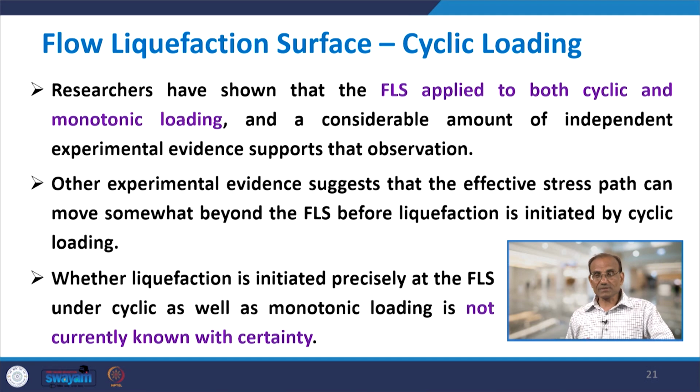So far we have discussed monotonic loading, but what happens if I change to cyclic loading? Researchers have shown that the FLS applies to both cyclic and monotonic loading. It is not only for monotonic loading, and a considerable amount of independent experimental evidence also supports this. Some experimental evidence suggests that the effective stress path can move somewhat beyond the FLS before liquefaction is initiated by cyclic loading. So, we are going to discuss now how cyclic loading affects this.